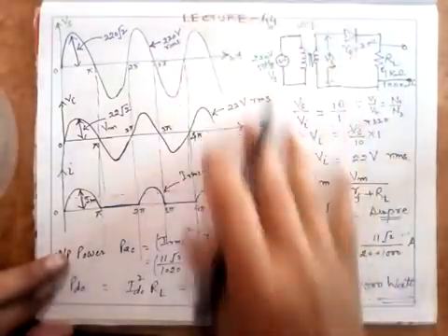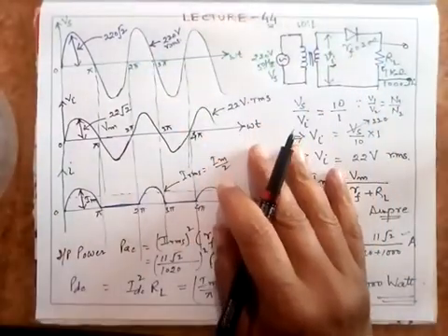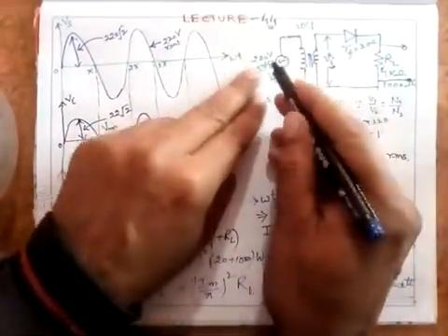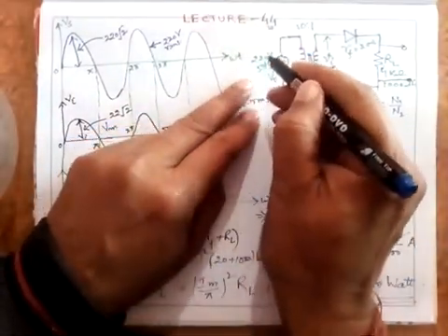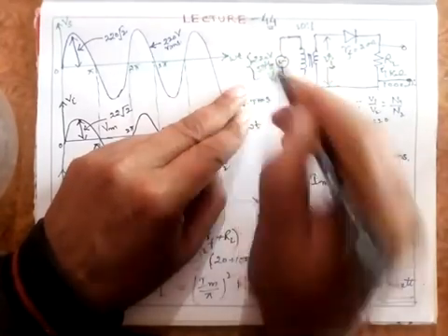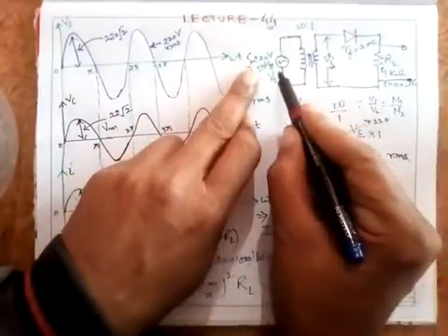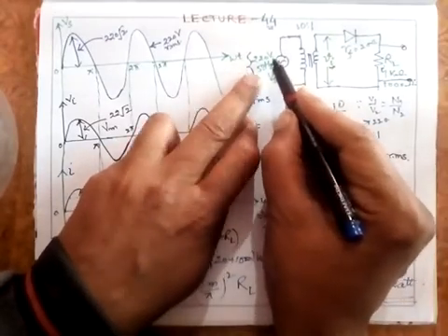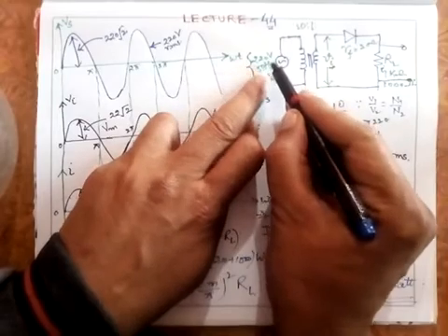So this is the problem that we have done. The very first thing was to understand the problem, and the main point in this problem, why I have done this problem with you, is that it was given that a sinusoidal signal of 220 volt 50 hertz is applied here, and it is very important to understand what this means. This means that this voltage is RMS voltage.